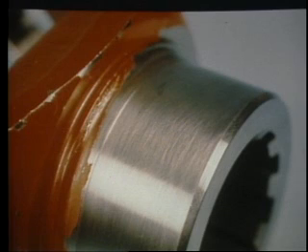Further, the fine scratches formed by the abrasive cloth could not be made absolutely perpendicular to the center line of the yoke spline. These scratches will either force oil under the seal or draw contamination into the seal. The yoke shown in this slide should not be used because of the improper surface finish formed when someone tried to repair the sealing surface with crocus cloth.